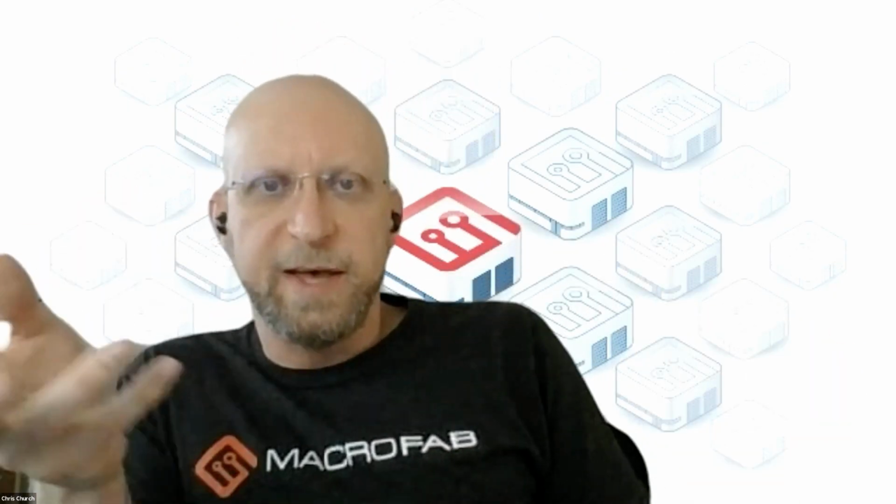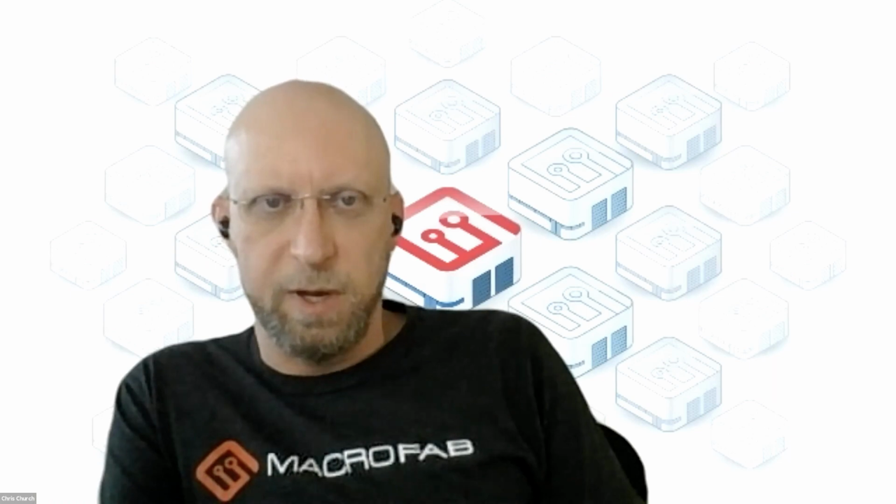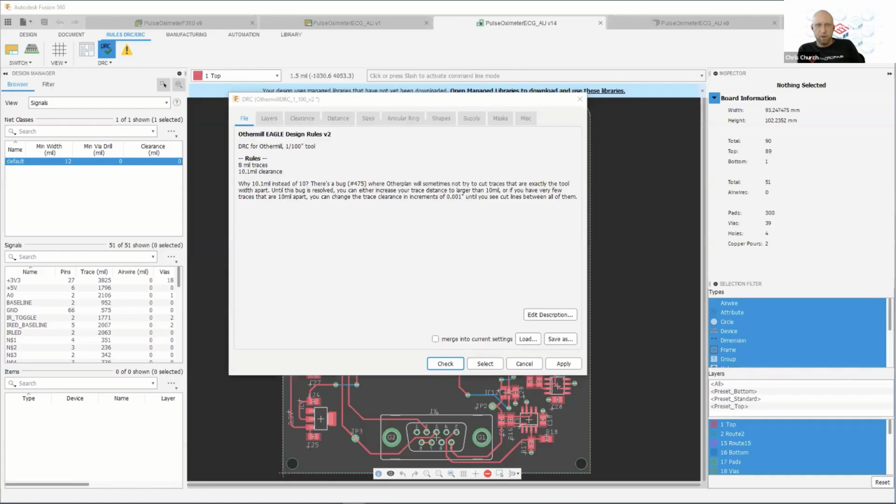So Larry asked, in the diagram I showed of the via, why weren't all of the middle layers plated on both sides? That was because it's just the drawing. We probably could have added the plating on both sides on those. And then let's see, what width size is used for impedance calculation? Hideo asks this, if the trace width is different at the top and bottom.